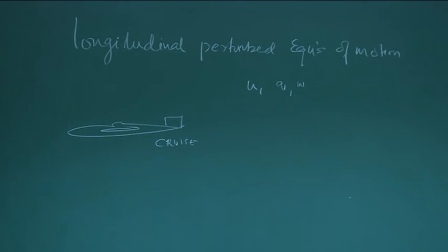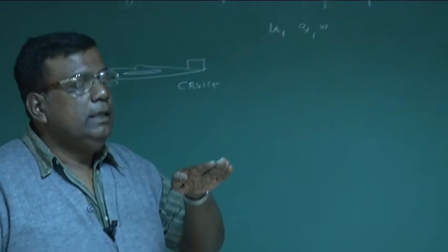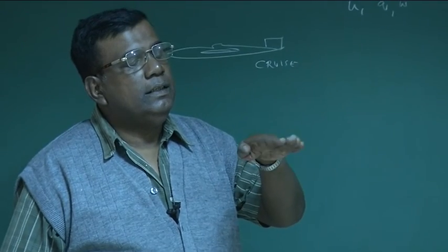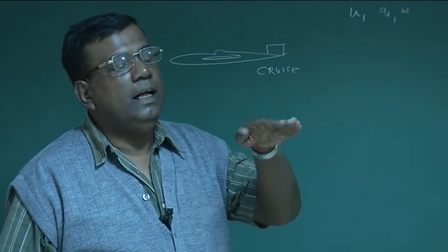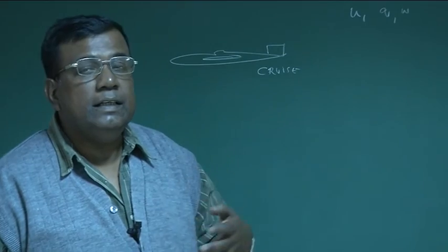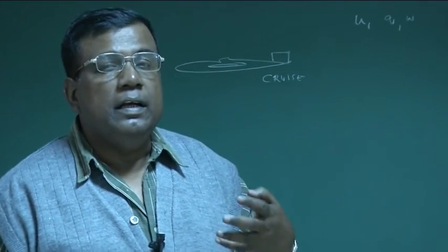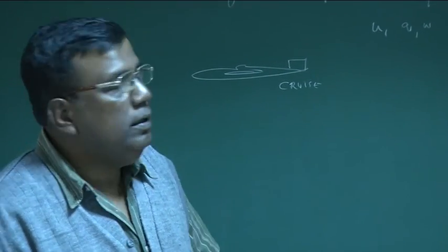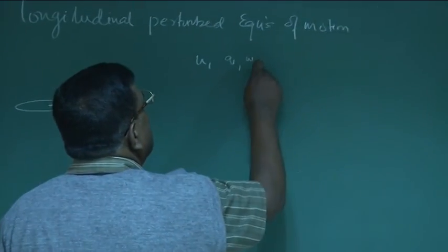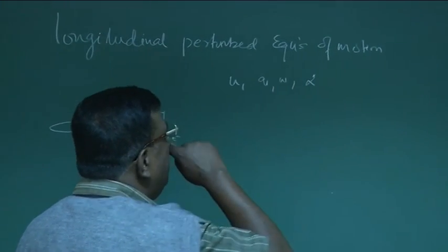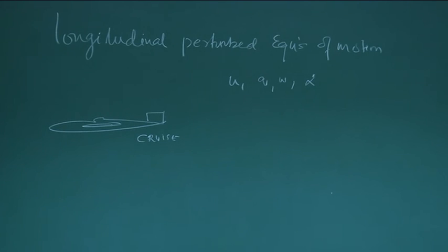And also we know that as this airplane is doing pitching like this and also doing plunging like this, there will be a change in alpha. We call rate of change of alpha becomes important, and we also note down that alpha dot also will play important role. Important role where?